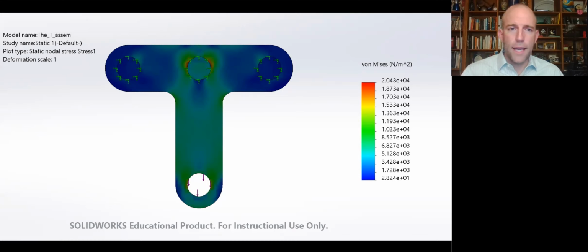So we've verified that just thinking about the way the shape deforms can often make an accurate prediction about whether your assumptions about the free body diagram are correct. Now, the purpose of this is not to say that every time you have three holes, only the middle hole sees force, right? It's that when you have indeterminacy, deformation is what tells you where the forces are, and often you can make a simple assumption that's consistent with that deformation.